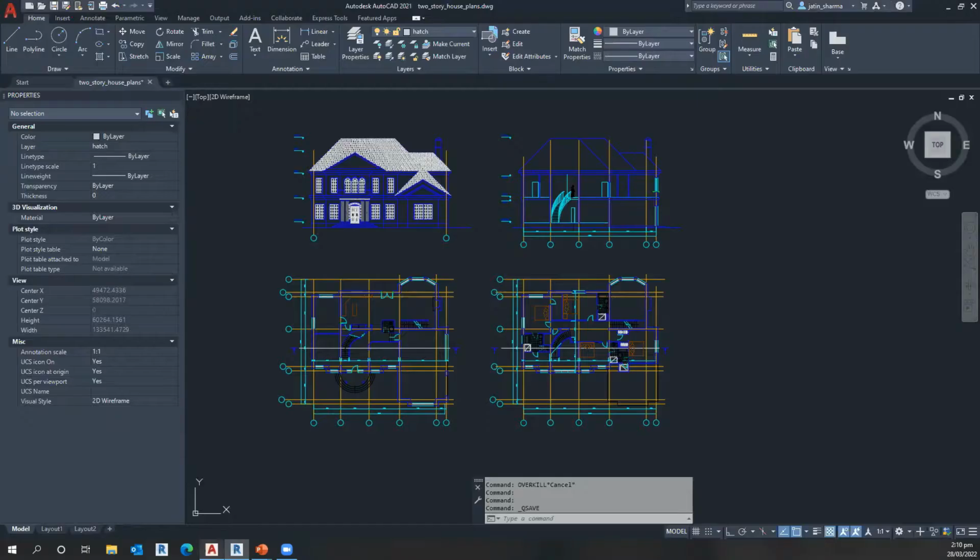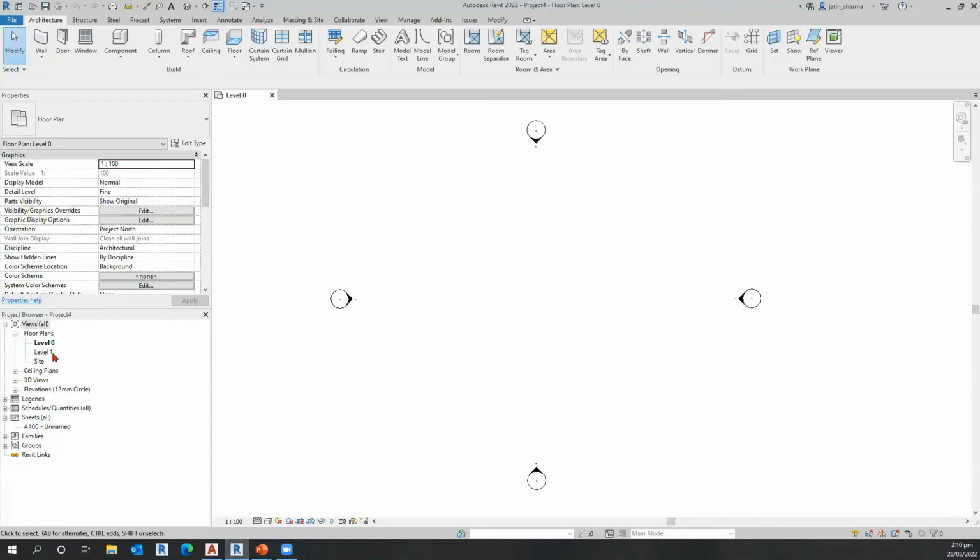Now, looking at the design, we can have a pretty rough idea of what this building is going to be, right? It's a 2-story building. It's got 2 floors and we've got a roof over here. And that's mimicked back in my typical Revit project template. We've got a level 0 and level 1. Yeah, that could be named a little bit better, but we've got our 4 elevation bubbles. And it all seems pretty straightforward. So I feel fairly good bringing this straight into this environment.